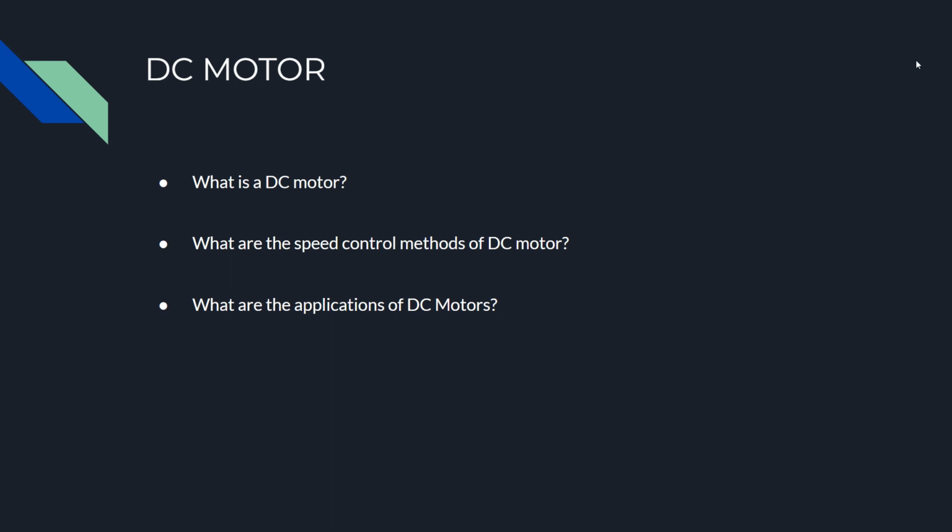A DC motor or direct current motor is an electrical machine that transforms electrical energy into mechanical energy by creating a magnetic field that is powered by direct current. When a DC motor is powered, a magnetic field is created in its stator. The field attracts and repels magnets on the rotor. This causes the rotor to rotate. To keep the rotor continually rotating, the commutator that is attached to brushes connected to the power source supply current to the motor wire windings.